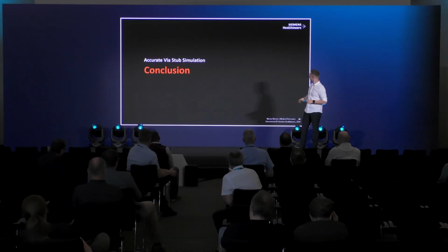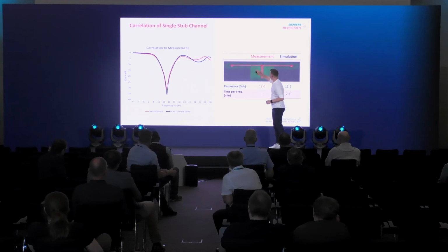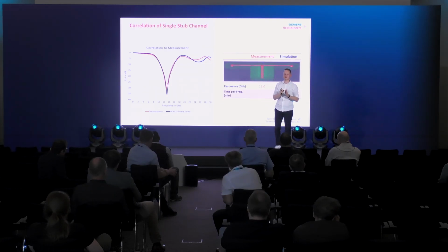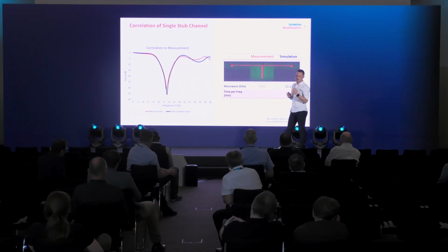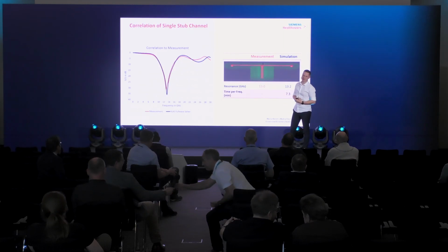If you look at this channel, the vias are like here, and you have only a trace. The perfect thing would be measuring and simulating right here, to not even get the effect of the trace. So I really want to isolate the effect of the stub resonance, and how the stub resonance is affected by length and by capacitive loading. Okay, got it. Thank you. You're welcome.